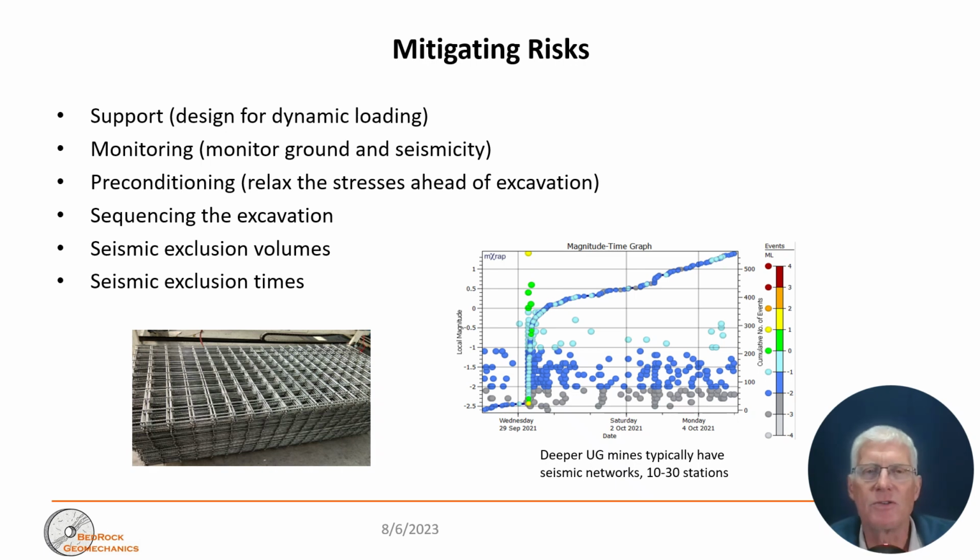So now just a few words about mitigating risks. What we know about mitigating earthquake risks at the normal civil engineering human scale is that predicting seismic events is really very difficult. It's better to spend your money on engineering and checking whether buildings and structures like freeway bridges are strong enough to withstand the main seismic events you expect in a particular region.